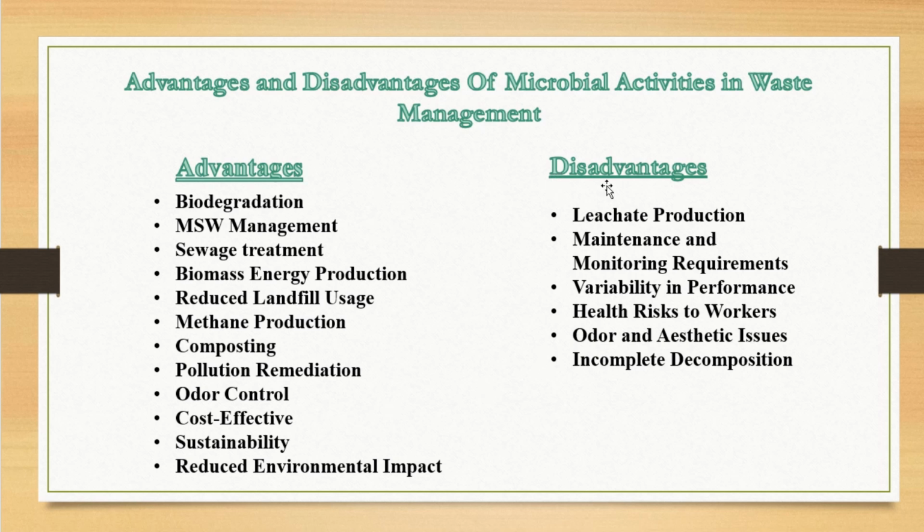The disadvantages are following. Leachate production, when we are not taking proper parameters of municipal solid waste management with the help of microbial activities, leachate production will take place, and it will percolate in the soil and go to the underground water, and it will pollute the groundwater. So the major concern about leachate production will also be a concern point.